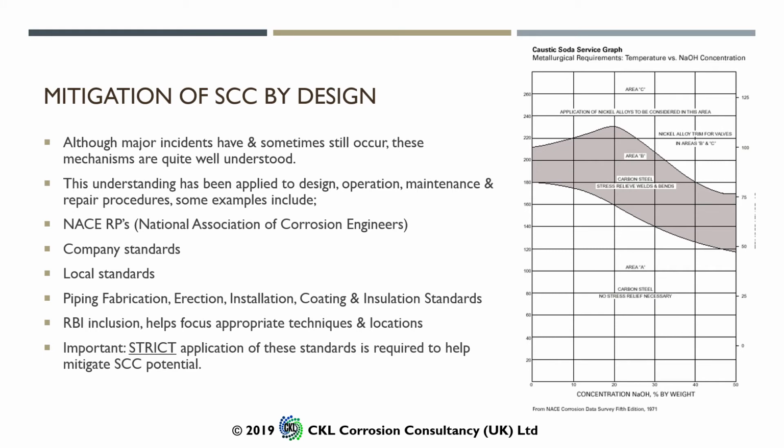There are also company standards. The major oil refining companies have their own company standards within which they specify post-weld heat treatment requirements, and considerations for items entering caustic service and amine service.